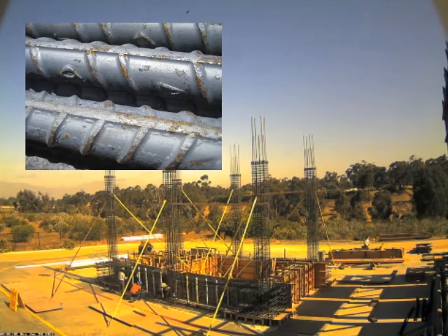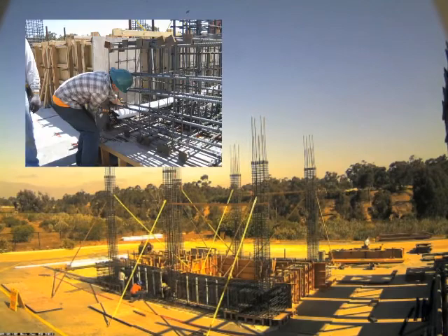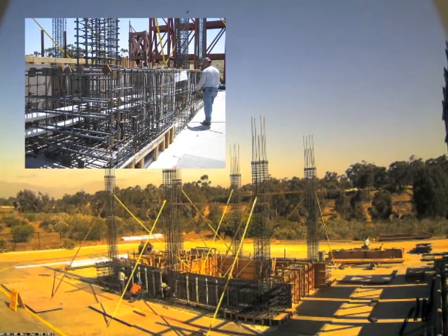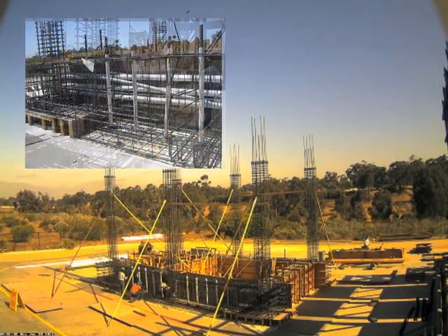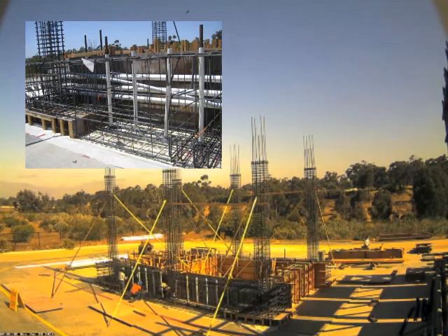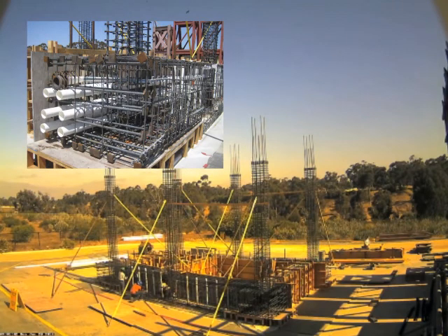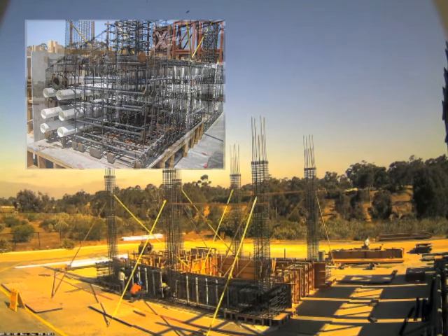In many structural applications, high-strength steel rods are used to pre-stress reinforced concrete and ultimately improve the integrity of the structure. In pre-stressed members, compressive stresses are introduced into the concrete to reduce the tensile stresses resulting from applied loads, including the dead load. Pre-stressing can be accomplished either by pre-tensioning or post-tensioning the concrete.